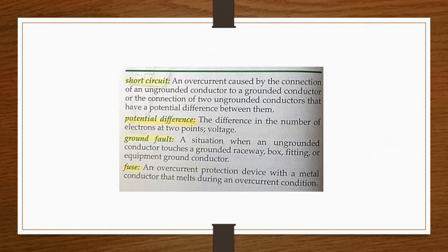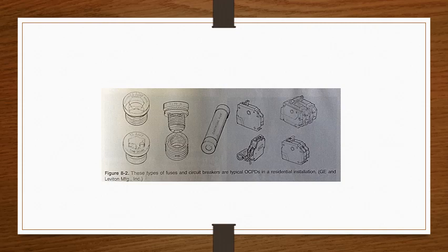Overload. An overload is a situation where equipment operates beyond the rated ampacity of that equipment or the conductors within the circuit. This type of overcurrent may occur when a motor experiences a large load and draws excessive current for more than a short duration. The overload could also be caused by excessive utilization equipment.